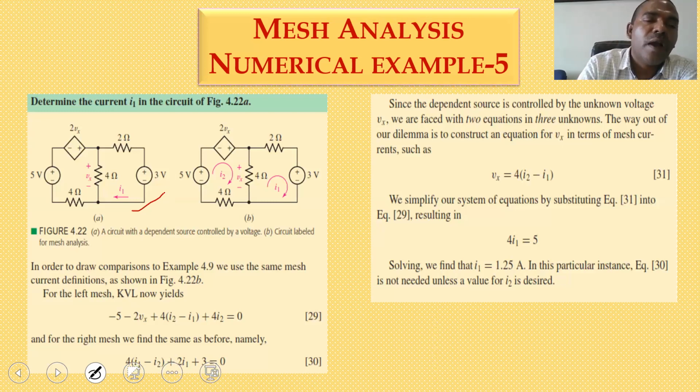Okay. So now I am going for the loop currents. I1 and I2, because 2 loops are there, I am taking clockwise direction. So with respect to the source, the loop is I1 current. With respect to the left hand side, the loop current is I2. So now I am writing the KVL equations. So the first loop, I am writing with respect to the left hand side.